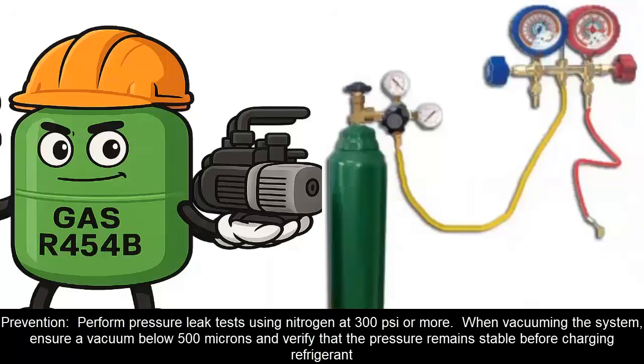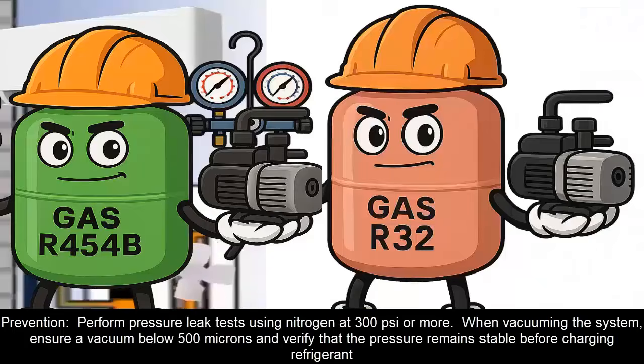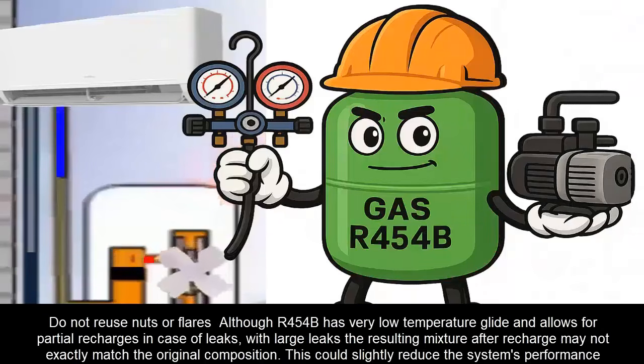Prevention: perform pressure leak tests using nitrogen at 300 psi or more. When vacuuming the system, ensure a vacuum below 500 microns and verify that the pressure remains stable before charging refrigerant. Do not reuse nuts or flares.